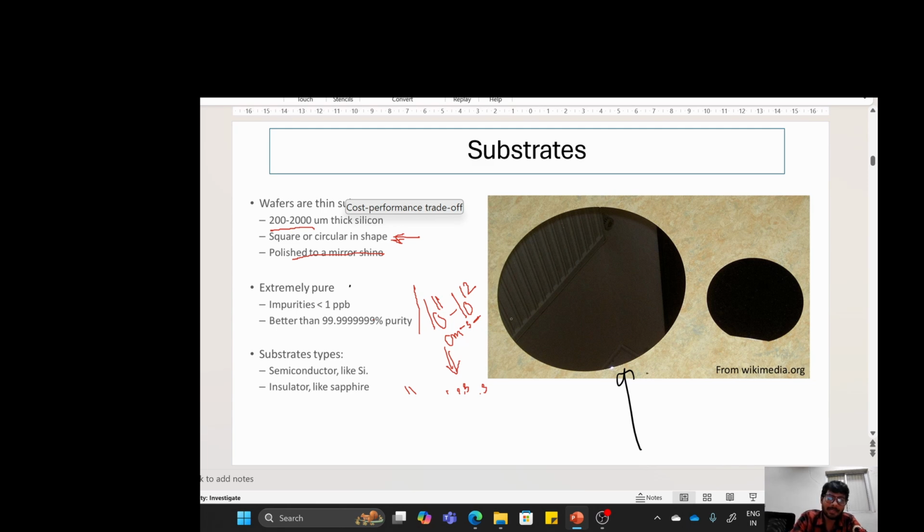And extremely pure silicon you can get, because there are some methods like the Czochralski method and the zone refining method. Through that these wafers are prepared, and you can get very pure silicon, so as to reduce the traps, okay. That's why you can get a very good mobility in these. That is why silicon is still dominating in the market, okay.